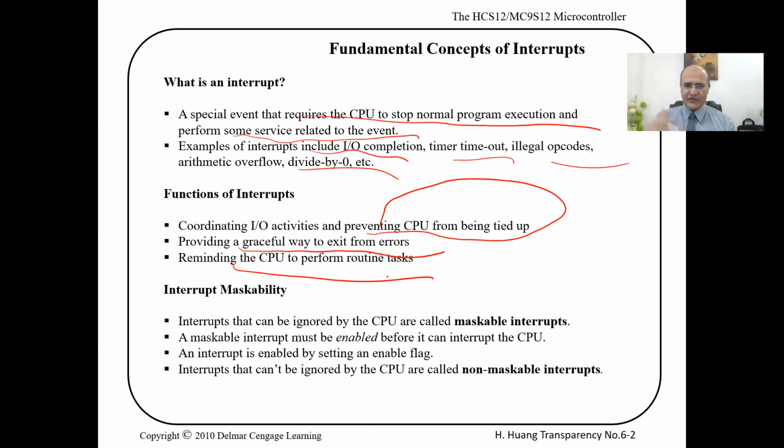And by the way, when we mentioned the watchdog timer, at the end of the day, it is special, but it is a timer that overflows and causes the program counter to go out of sequence, right? It sends it back to the first instruction, causing a reset. A reset is an interrupt.